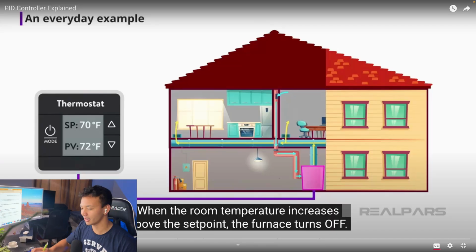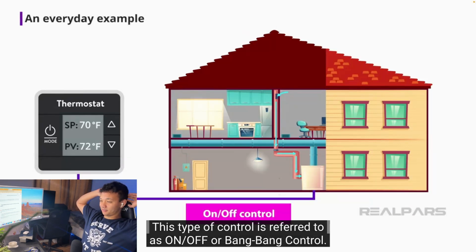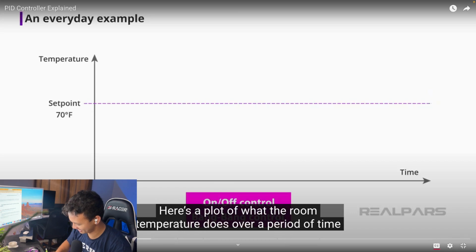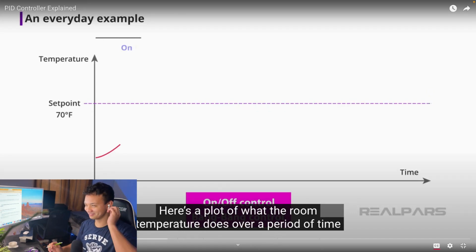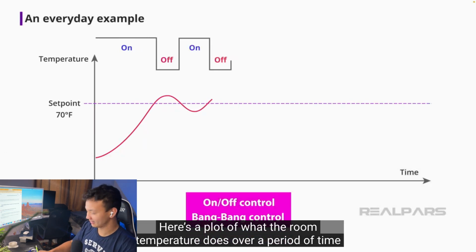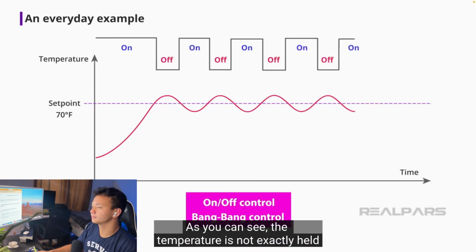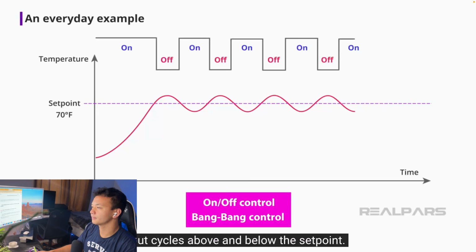I don't get it. This type of control is referred to as on-off or bang-bang control. Bang-bang control. Okay, so let's write that down. Here's a plot of what the room temperature does over a period of time as the furnace turns on and off. As you can see, the temperature is not exactly held at the set point of 70 degrees Fahrenheit, but cycles above and below the set point.